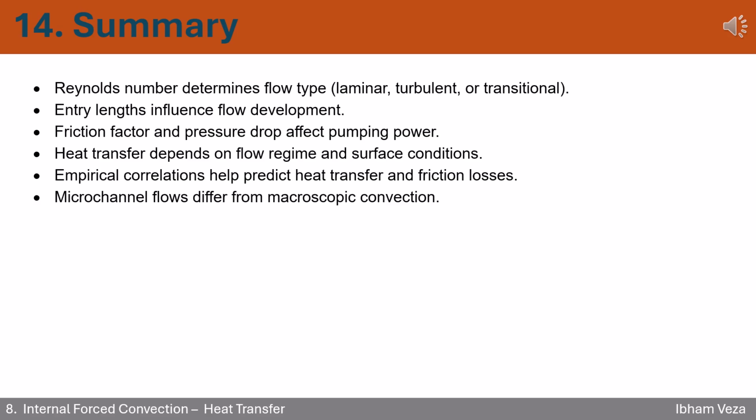Pumping power is directly affected by friction factor and pressure drop, so minimizing losses is crucial in design. Heat transfer is not just about the fluid, it's also about the regime it's in and how the surface interacts with the flow. Empirical correlations are your practical tools. They save you from complicated calculations while still giving reliable estimates.